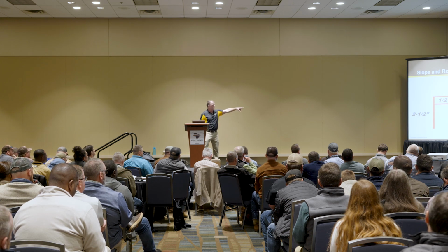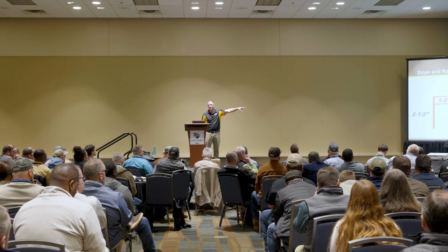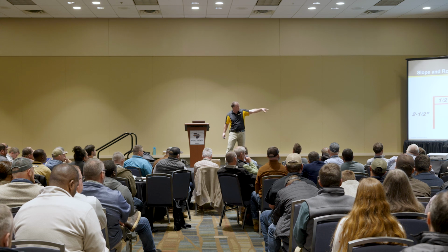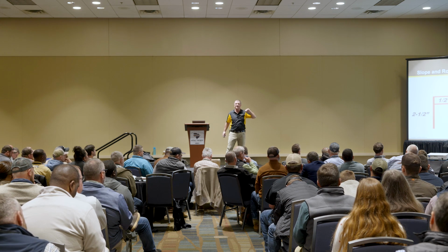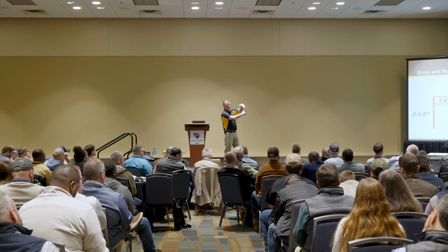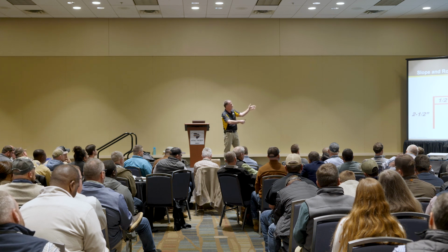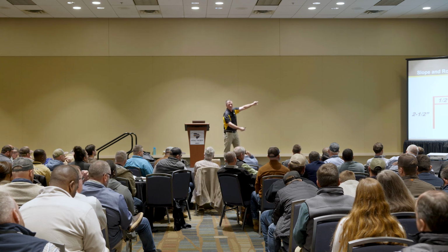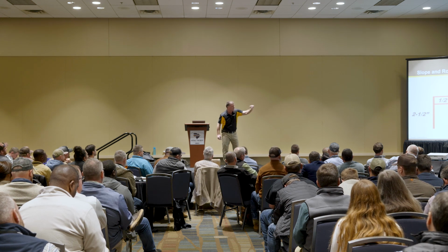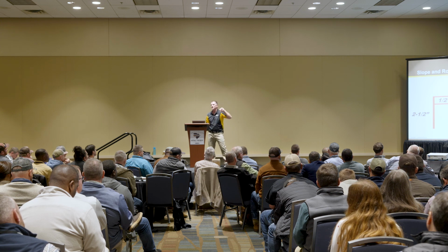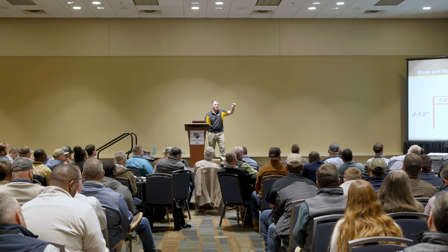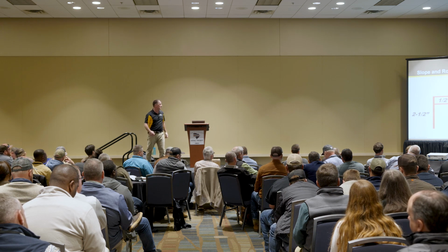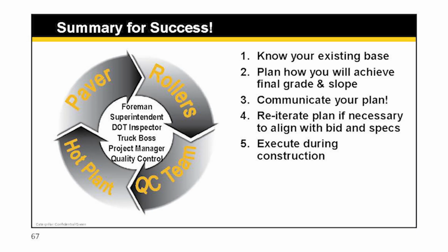And that's, again, when we're talking about cross slope, that's what I've got to just be aware of, right? Because if I've got that green section there in the middle on the right, if that's my pavement and I'm at 2% and I come in and roll it, it's going to roll down more on that thicker edge, right? So what was 2% behind the paver is now the bottom green, it's 1.5%, because it rolled down more on that thicker edge. So that's where you have to factor it in the paving part of it, your loose mix coming out behind the screed.